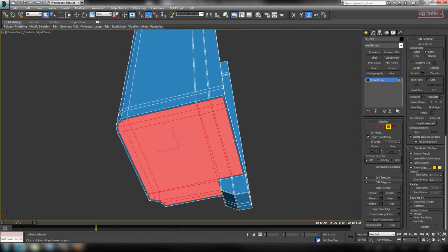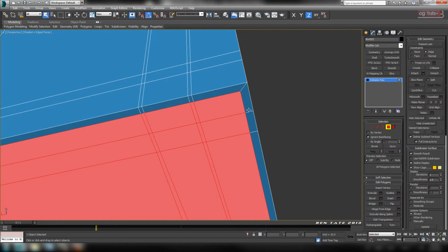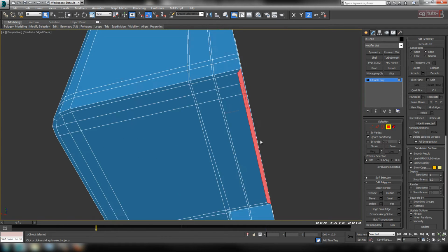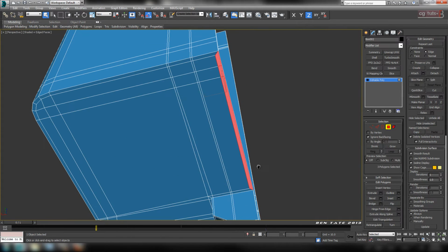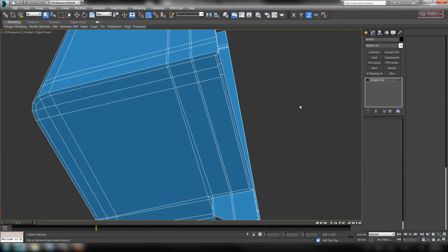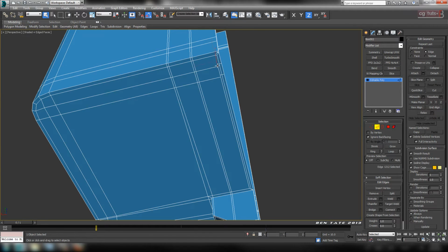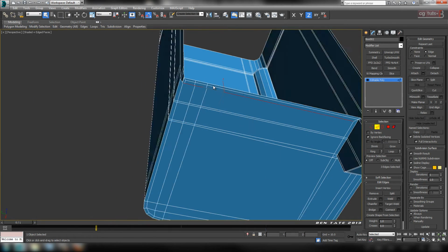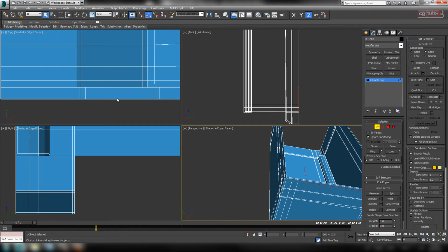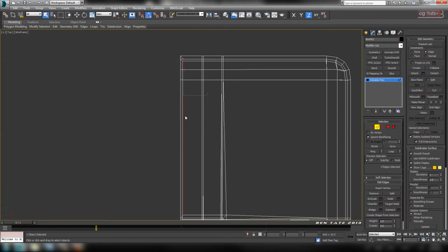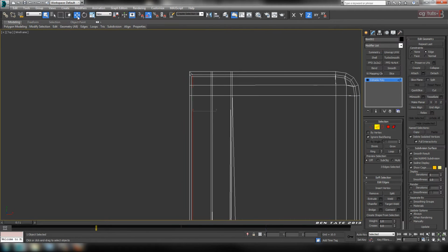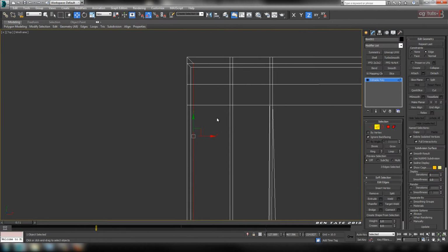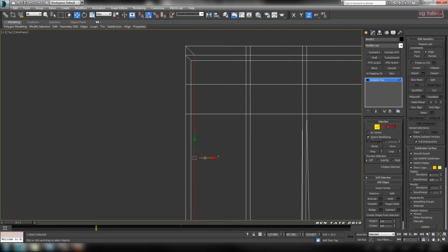One thing we definitely don't want is these inner polygons here. Let's actually grab these. Okay, those center ones there, the 3 of them, we'll delete them. And let's go to edge, and we're going to grab these 3 edges, which is right next to the ones we just deleted out. And we'll just go into the top view here, into wireframe F3, and move these over to the center so that they're not pushed in like this. Okay, and we actually have it on the top as well.